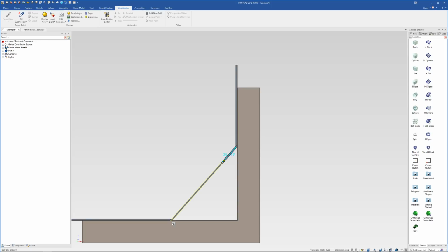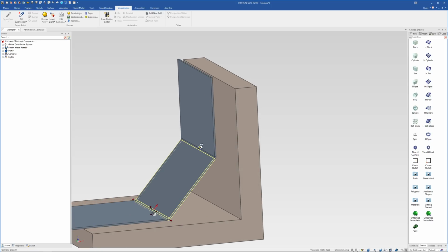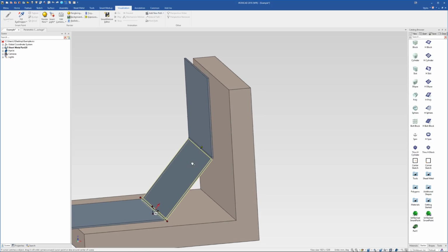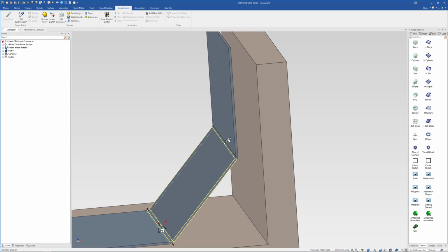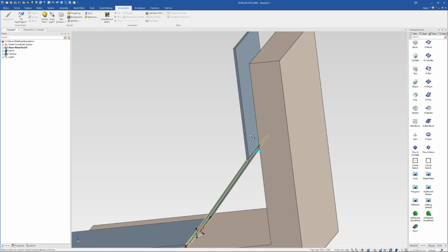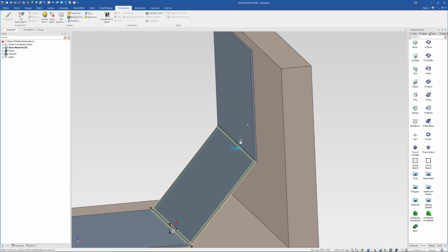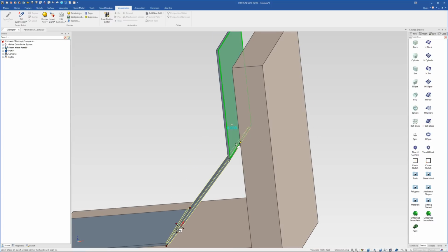What you can do with sheet metal parts is change the snap point you're using for that piece of sheet metal. If you right click on the endpoint of a bend, you can set the handle snap point, and you can also set its orientation. I'm going to set the handle snap point first to be onto this face. That's the face we want to align with the wall. Then I'll right click and do set handle orientation, click perpendicular to face, and then click on that face.